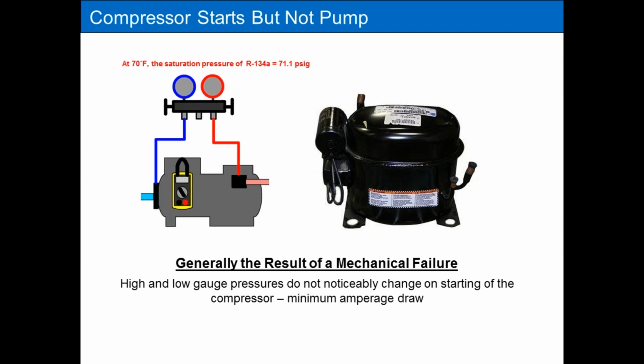So the next step is you plug the compressor in, you turn the unit on and see what happens to your pressures, even though they're low at this point, right? And you know that it's lost refrigerant, so that's part of the problem. But you still want to see if that compressor has the ability to pump. So you plug it in, turn it on, and you want to see your low side pressure drop and your high side pressure go up. Now I can't tell you where they should go because the pressures are going to be wrong, but you want to see a change, right?